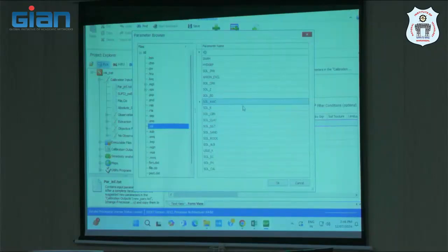It is one of the most important because of what available water is: field capacity minus wilting point. If there is more space, more water will occupy it, so surface runoff will be less. If that available water capacity depth is less, more surface runoff will happen. So that's why it is also one of the important parameters. We have added that soil parameter.